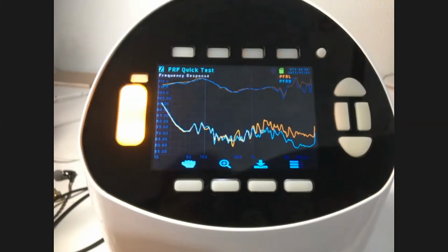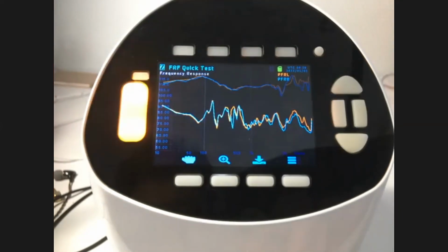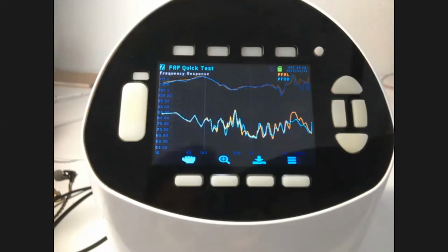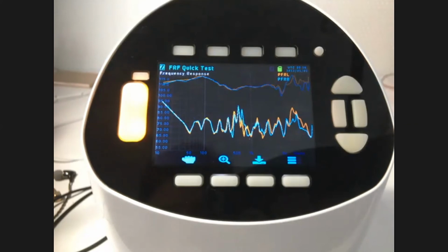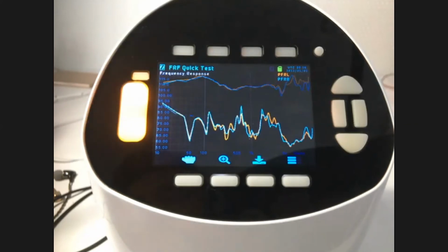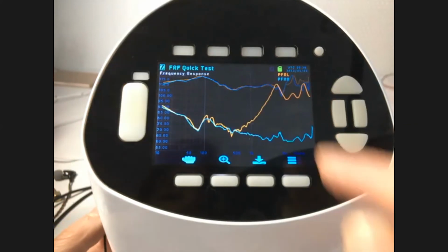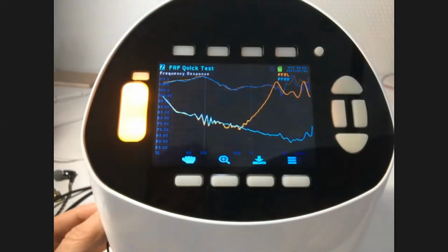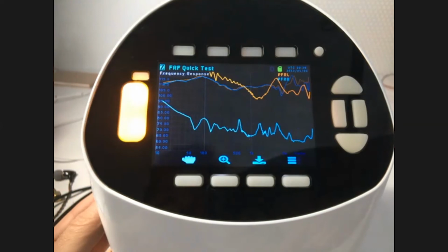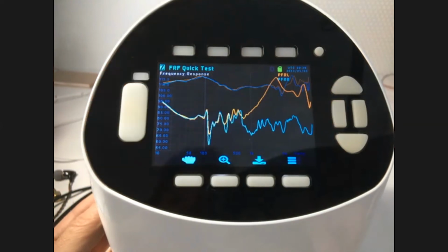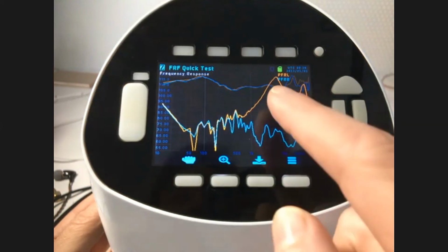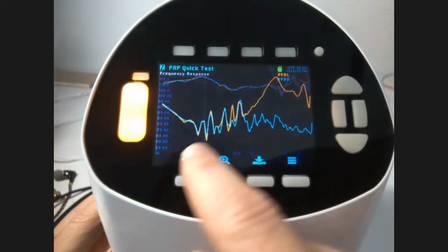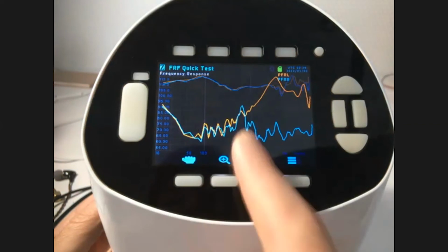I'll just put it next to the coupler. I'm not going to put the seal in. And you'll see that the frequency point at which it is acting like a speaker, let's say, is right up here. It's really high. Okay. So when I make this transition point, in a sense. Yeah, it is. So you call it a transition point. And so as with the speaker, below that resonant frequency, it just rolls off eventually to nothing.